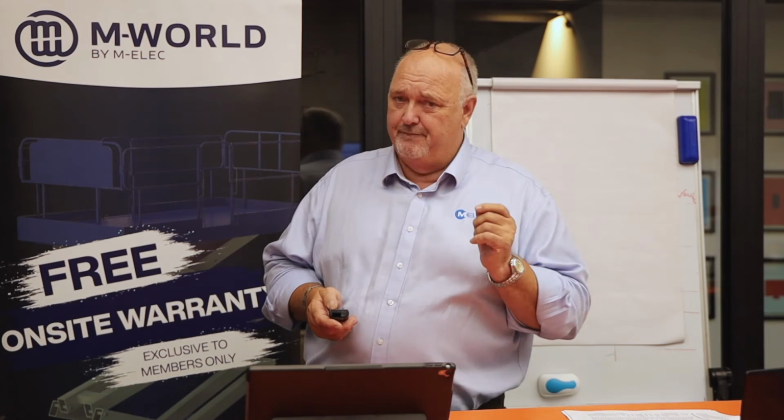It takes a matter of minutes, and it just means that when I install this, I'm going to be right on. If you're within a metre of it, you don't have to worry. If you're within 3 metres of it, you don't have to worry. But if you think you're going to be outside of 3 metres, do your voltage drop calculation, because it'll save you a lot of heartache later on down the track.